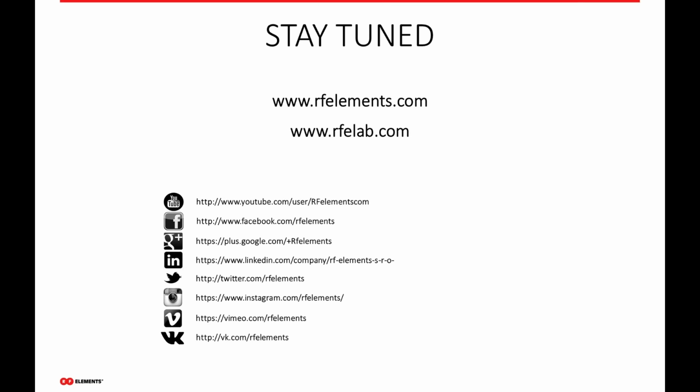So if you want it for full 256 QAM, maybe you're happy with 64 QAM. It's important to know your radio technology. Let's say, for instance, you're using a Prism radio from Ubiquiti. It does 256 QAM, so that's MCS 9. If you were to use a Cambium ePMP 2000 or even ePMP 1000, the maximum is 64 QAM at the moment, which is MCS 7. It's really important to know that, because if you have MCS 9 selected in a radio that's not capable of going there, it's going to show you that the distance you can go is much shorter than you would expect.